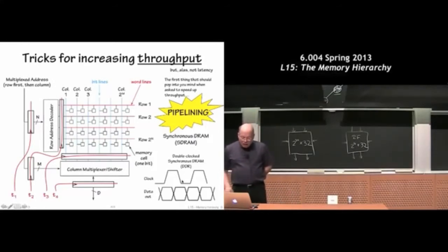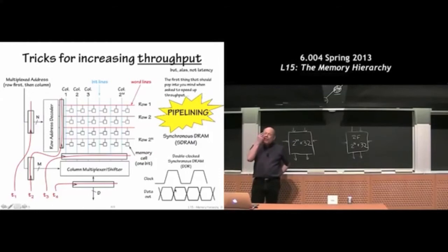The trouble is, this memory system actually has reasonably high throughput. It can sort of keep up with the consumption of the processor in terms of instructions, but sadly, it has a long latency. Once I have an address here, getting the first piece of data out of the memory is slow. After that, I get words every couple of nanoseconds. But getting that first word out can take quite a while as it gets processed through the pipeline.